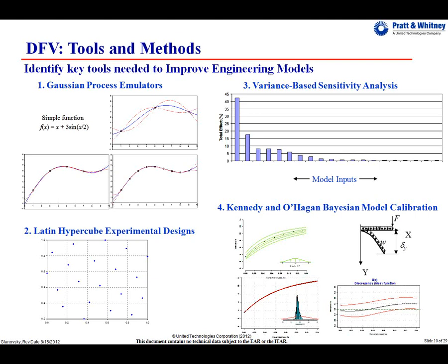Remember I mentioned that a lot of these computer codes took days and weeks to run. They were simply impractical. Well, by using some kind of an emulator to simulate what the model's output would be for a given set of input data, we had a simple mathematical model that could return a prediction in a matter of seconds or, at worst case, minutes, as opposed to the days or weeks it would have taken otherwise. Gaussian process emulators specifically, which quantify uncertainty in between the training data points, have been incredibly useful to us. Essentially, we just explained it to the engineers as it's a fancy version of a response surface design. That's good enough for them.